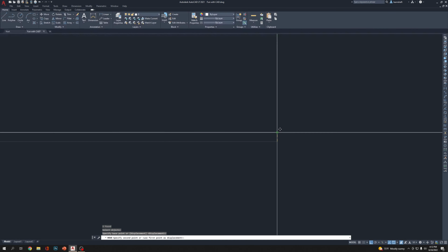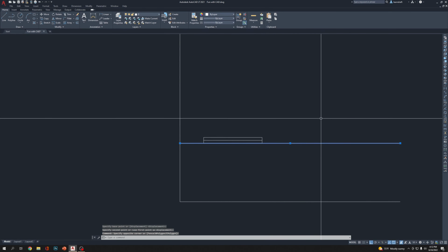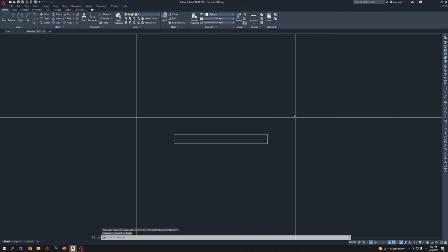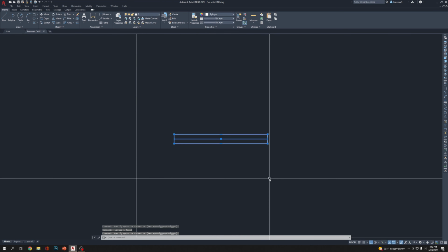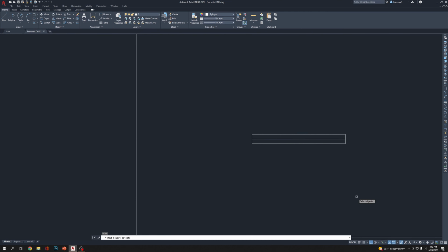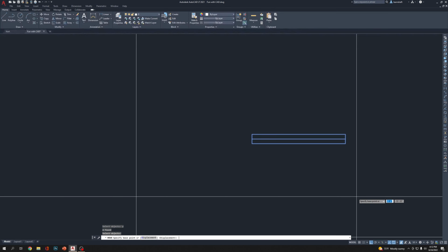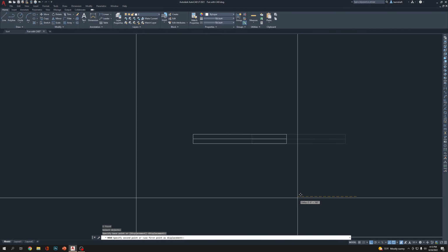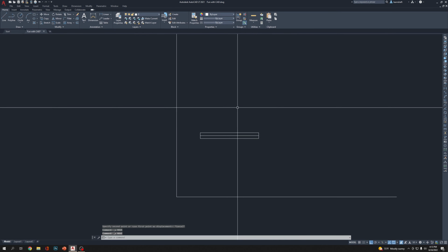I use move, enter, preview, enter, enter. It looks like this. So let's say I just moved this one here, right? I want to select this one, so I'm going to press enter to select the move command, and then P for previous, enter, then to select the object another enter, and then you click and move. Makes sense? Pressing escape and Control Z to bring it here.